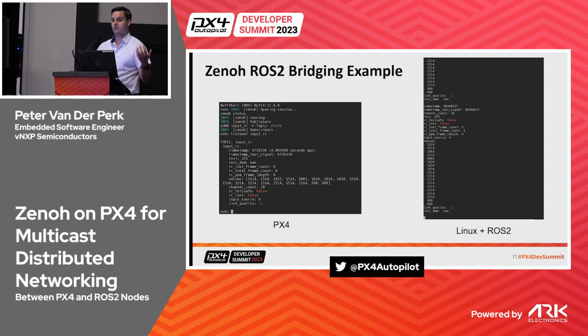So we can think about sensor messages, anything else. Right now, the implementation is quite basic, so I'm not doing rate limiting. So if you're really daring, you're going to send out your IMU, you're going to have the 1000 Hz IMU data out. Luckily, for now, it seems that it's quite performant. We can also keep up with that data stream, so we're not even overloading the FMU with that. But it still needs some fine-tuning.